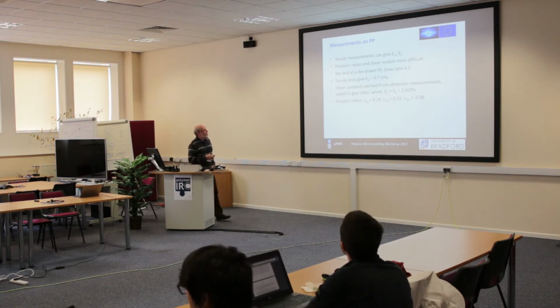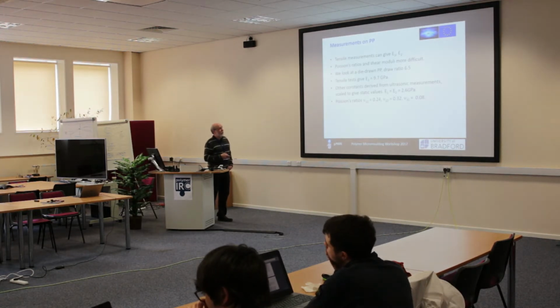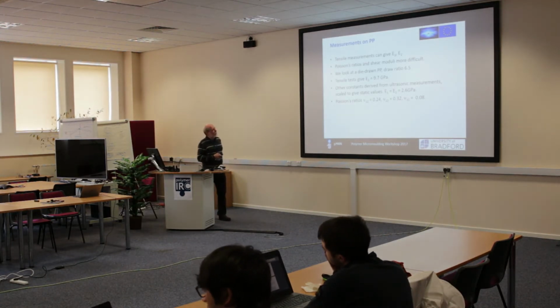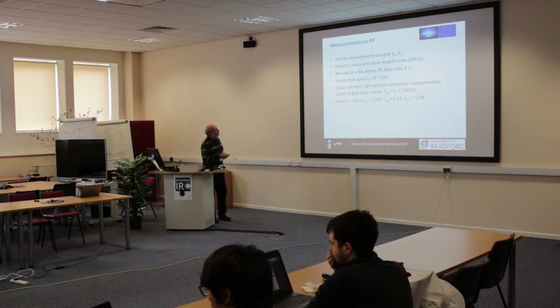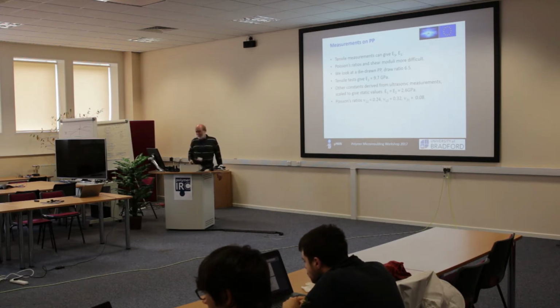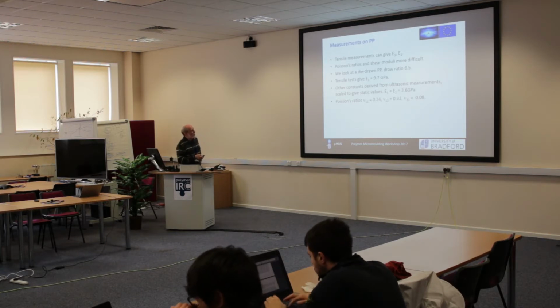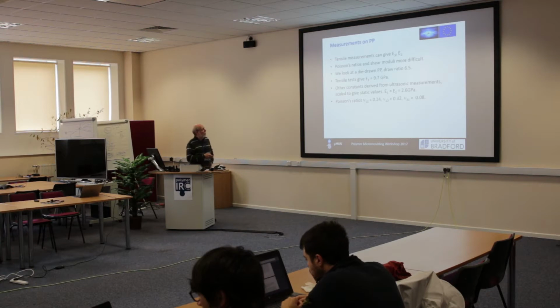We're looking at this particular polypropylene at a draw ratio of 6.5. We can measure E3, which will give us one of the elastic constants. So that's about 10 gigapascals, so that's increased it roughly by a factor, from about, I guess it was around 2 in the isotropic case.